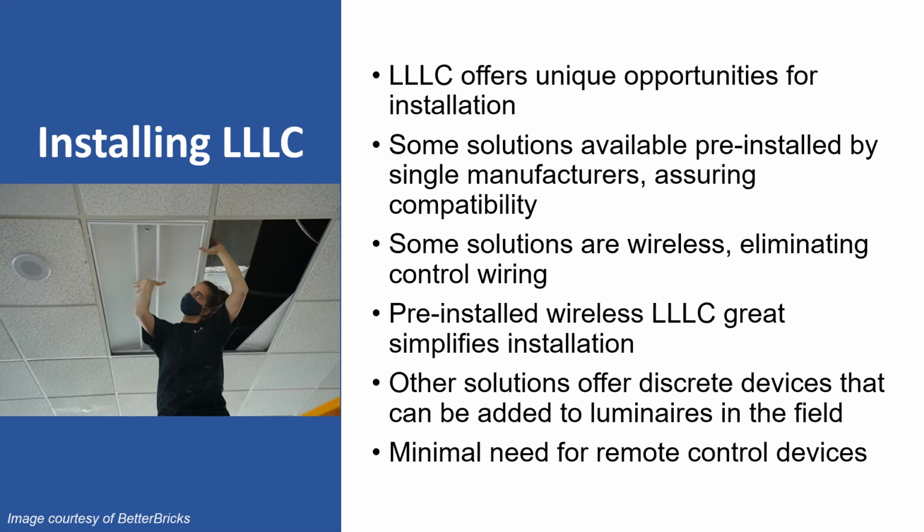Clever luminaire-level lighting control systems provide further potential benefit during installation because of the lack of supporting hardware in many cases except for switches. If it is a wireless solution, no control wiring is required. This can be particularly advantageous in a lighting upgrade project in an existing building, where utility rebates may be available to reduce cost.